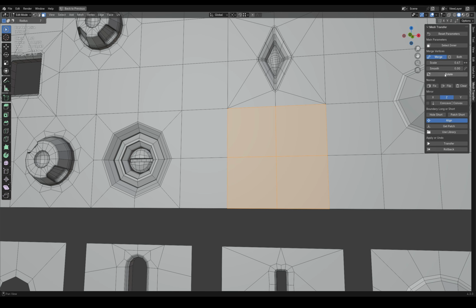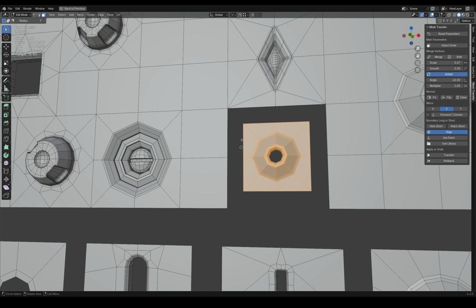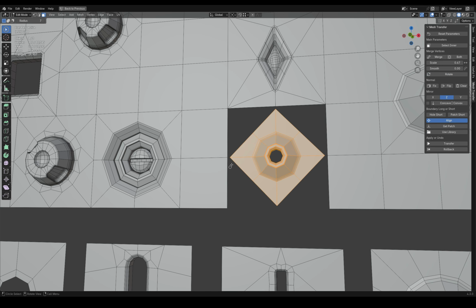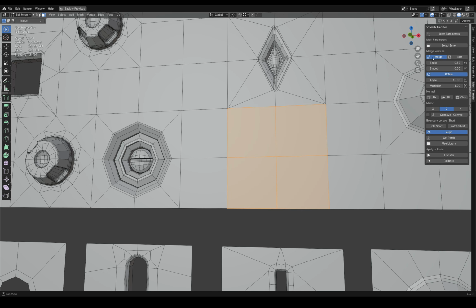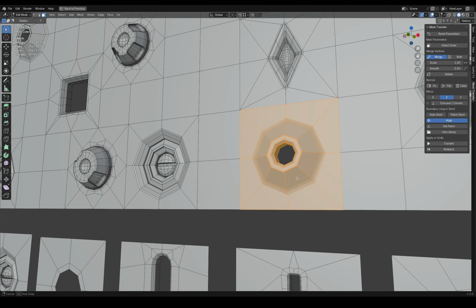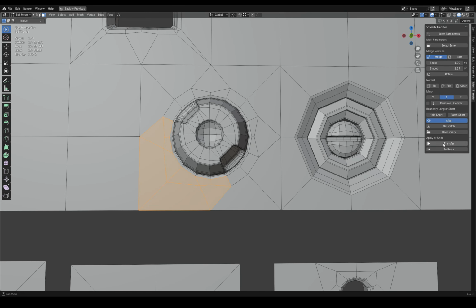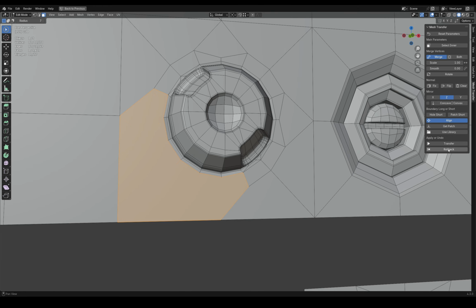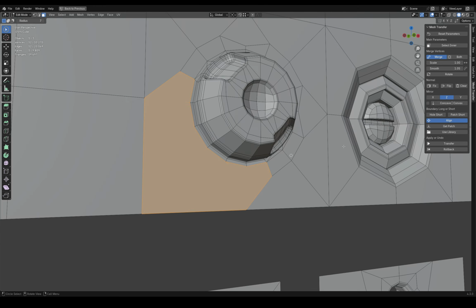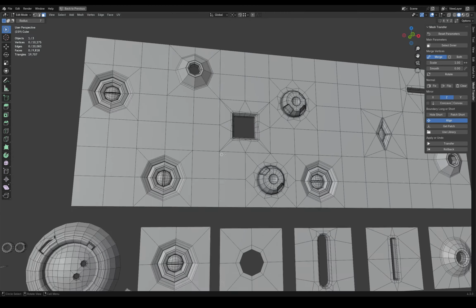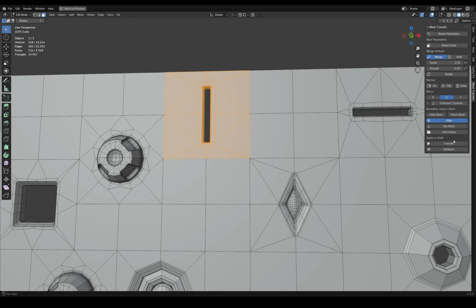When a pattern has border edges of equal length, it may sometimes be rotated incorrectly around its local z-axis. For this, we can use the Rotate parameter. The Smooth parameter smooths the entire internal mesh without affecting the boundary vertices. This can be used most often on flat surfaces to distribute the mesh more evenly. Now I will show you another example where you may need the Rotate parameter.